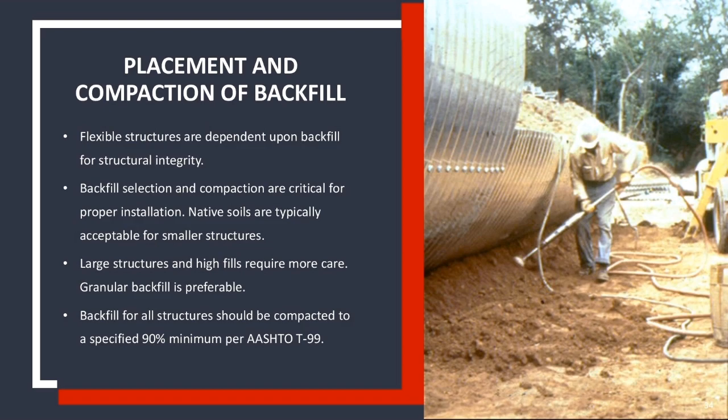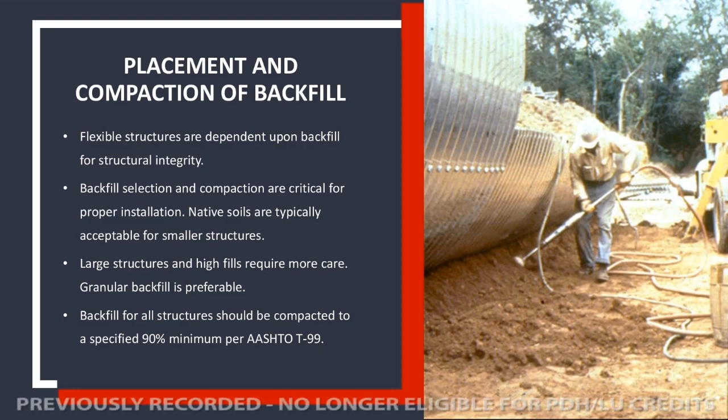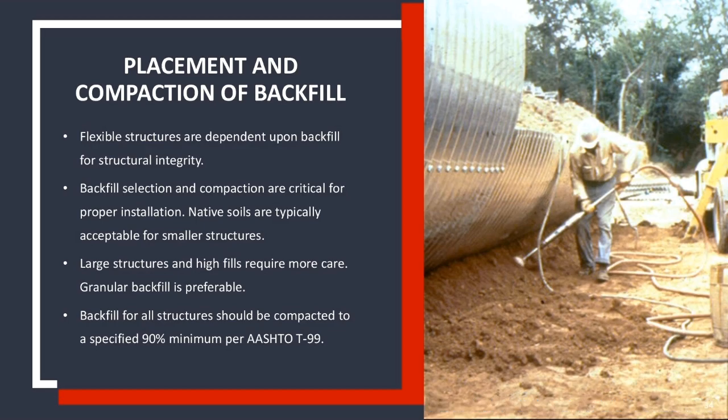So let's really get into the placement and the compaction of the backfill. Like we mentioned earlier, flexible structures are completely dependent on the backfill for the structural integrity. And so backfill selection and compaction are critical for proper installation. Like we mentioned, native soils are typically acceptable for smaller structures, but when you get into bigger structures, you really want to start looking at a better backfill material.